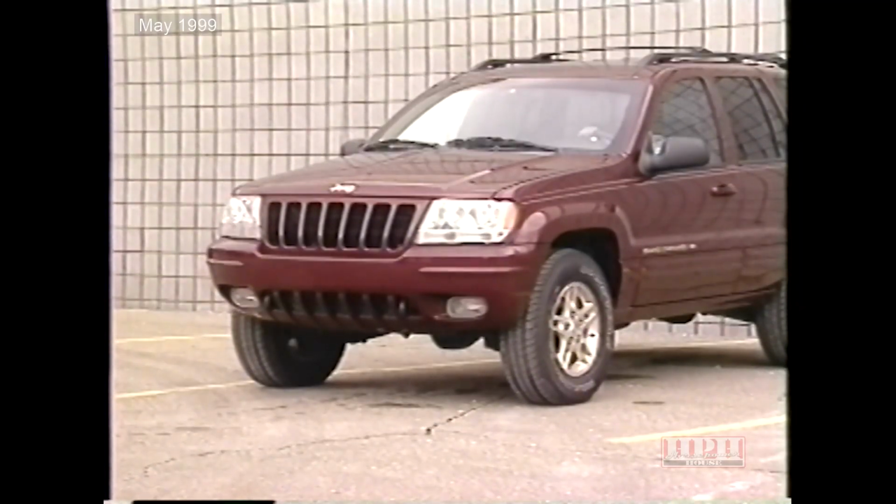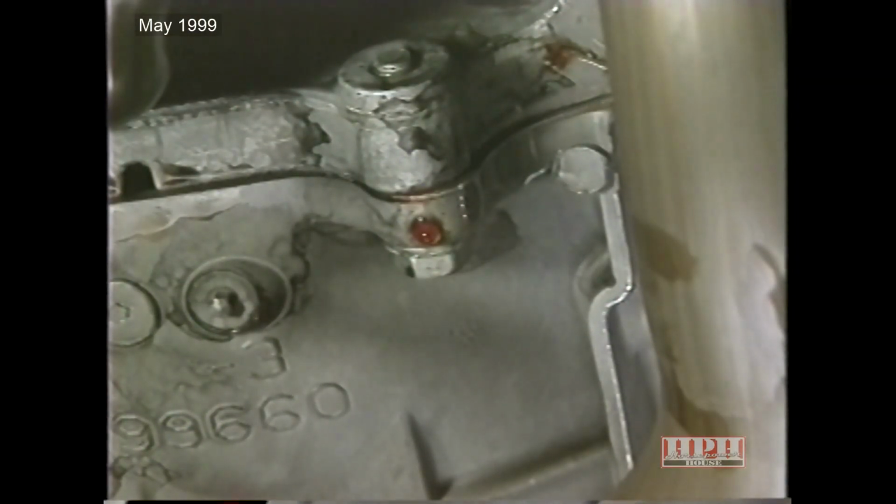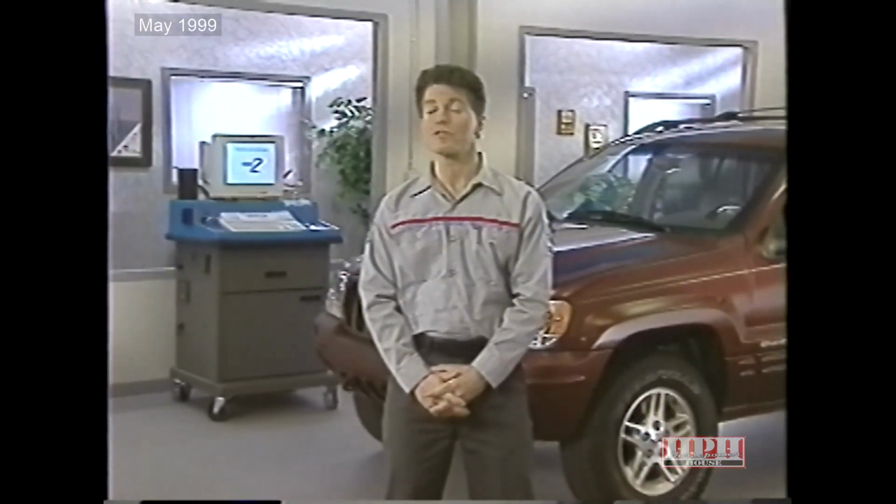If the transmission has too much fluid, delayed or erratic shifting can result. And like engines, too much transmission fluid can cause leaks. As you can see, maintaining proper fluid levels is important to overall vehicle performance.